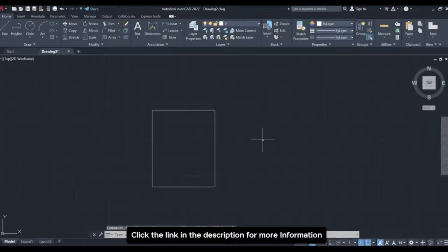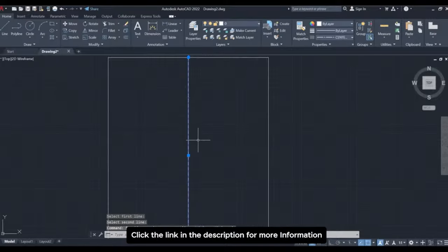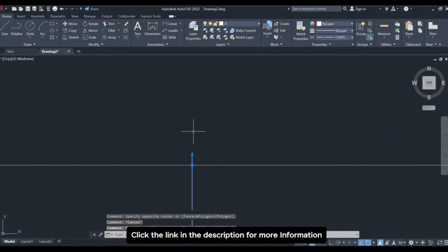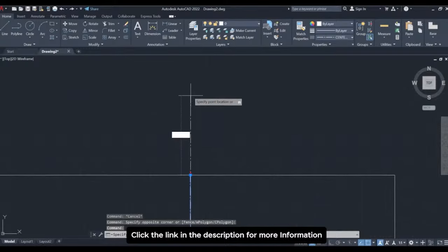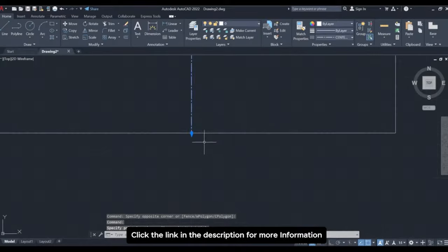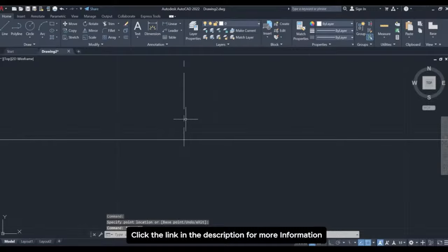So we've seen center line in the previous session, so we're going to use that once again. That's CL for center line, then select the first line and then select the second line. And you'll see that you have this line over here, which is the center line being created. And also when you select this line, if you zoom to the top over here, you'll see there's a tiny little arrow, because this arrow is going to let you extend beyond the limits of the body. All right. So you can manually just select this and extend it like that.